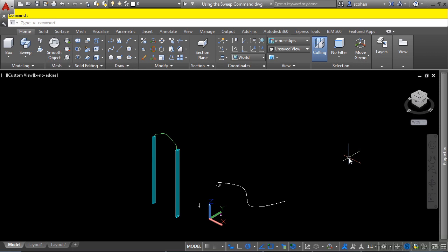And of course, if you select an open geometry instead of a closed loop, then it creates a surface model. By sweeping a profile along a path to create a model, you can create a complex model very quickly and easily without having to create and combine multiple models to achieve the required results. You'll be more productive and successful in sweeping profiles along a path if you know how to use the sweep command and its options to control the model's creation.